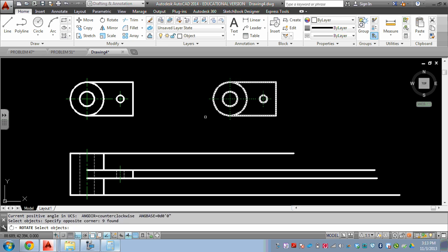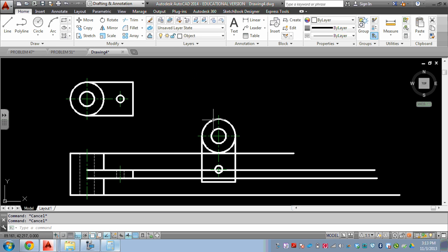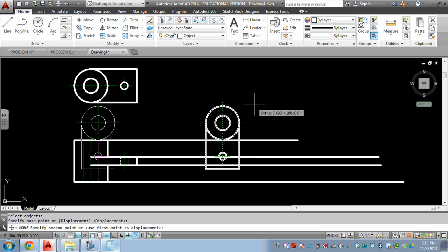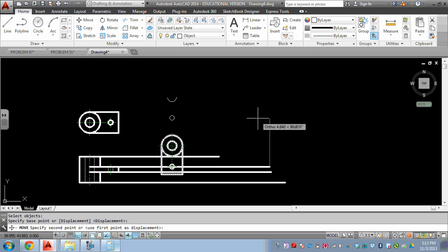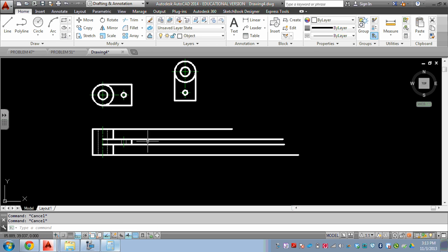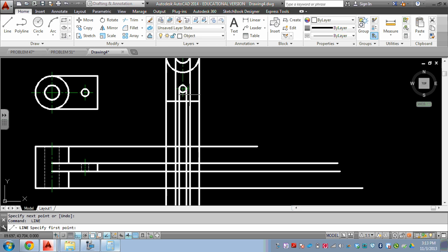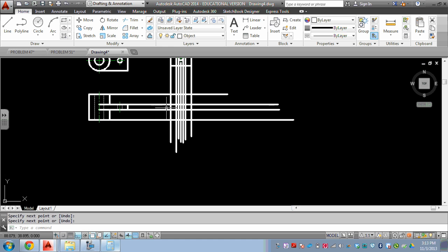Rotate, select this feature. We'll move this over, move it on up. Now you gotta be conscious of which side you're looking at. So we're doing the glass box, we're gonna be looking at it this way. If you flip that around, your hole's gonna be in the back and it'll be hidden. So let's just bring these features straight down. These are gonna be hidden now because we're looking through it. Beautiful, but confusing at this point.